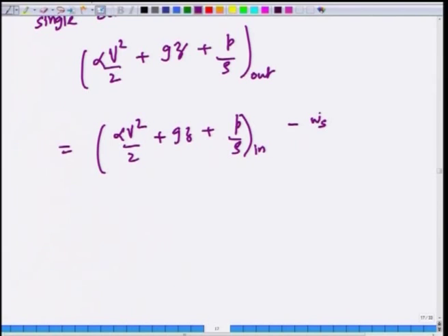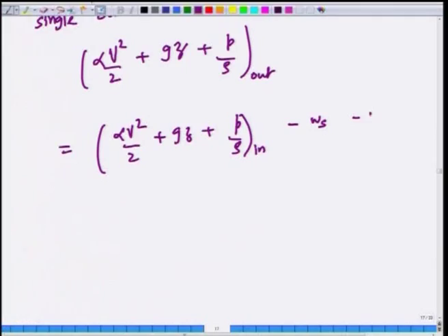We took the convention that work done by the CV on the surroundings is positive, and work done by the surroundings on the CV is negative. So if Ws is positive, that means work has been extracted out of the CV. If Ws is negative, then work is being put into the CV, minus the viscous losses. The viscous losses are always positive, WL is always greater than 0.